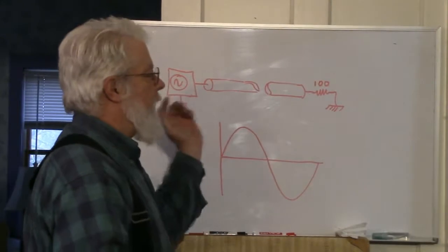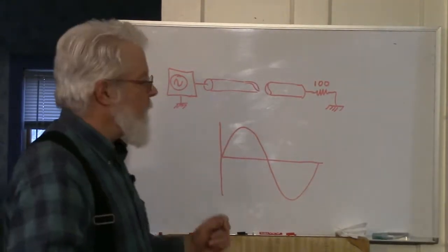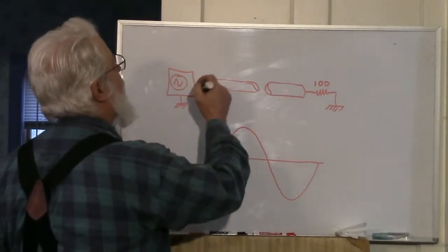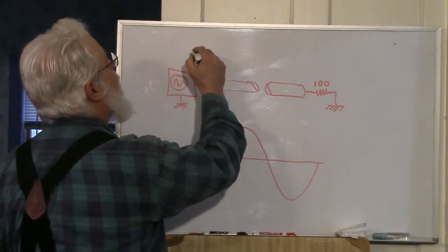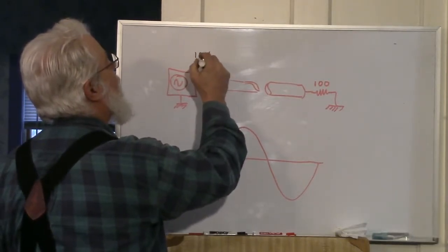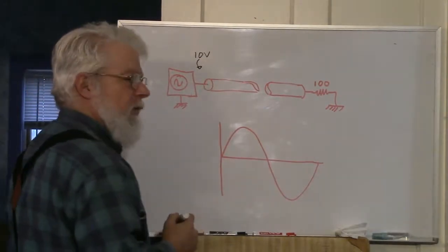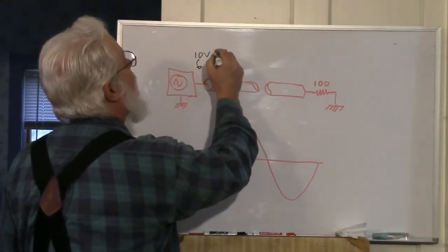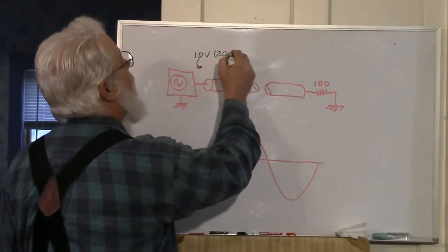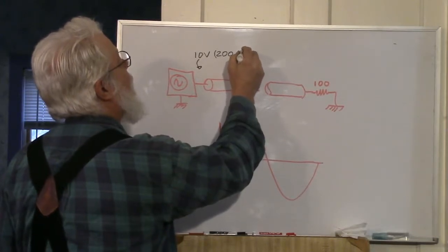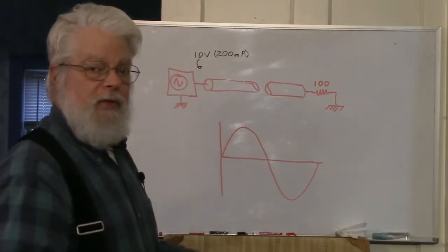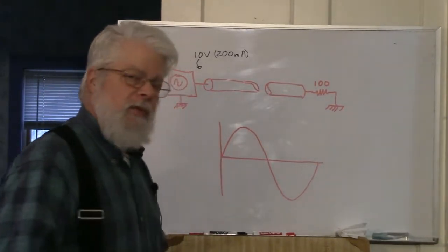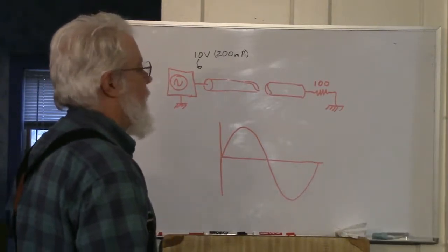So what's going to happen here is the signal is going to go out, and it's going to see a load that's too high. So at this end, we've measured our 10 volts of RF at this point. That's our initial level in the line. And at 50 ohms, that should be 200 milliamps. That's what should be flowing. This is what defines our characteristic impedance: the ratio of amperage to voltage, and you can determine the characteristic impedance of your line, among other things.